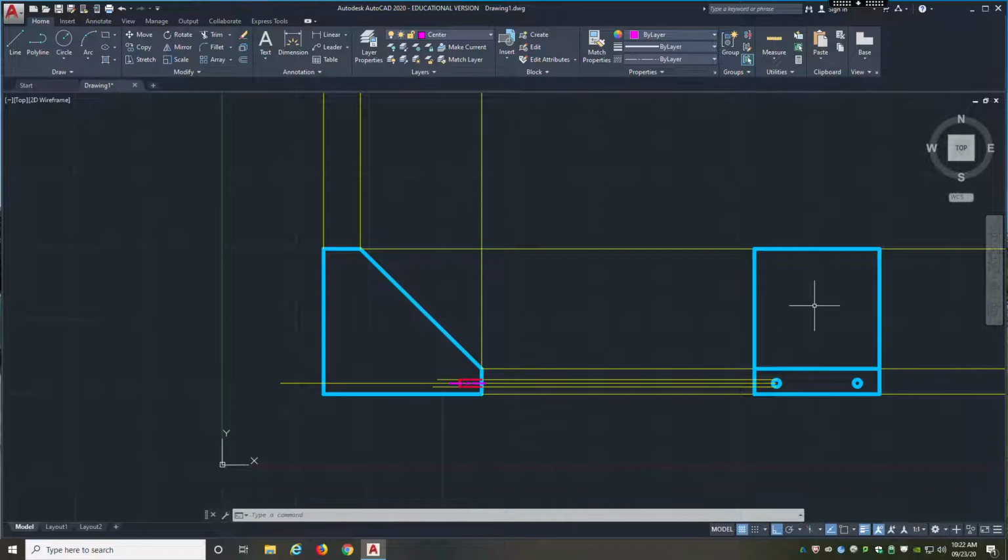Therefore, it's foreshortened, which is why a circular hole looks like an ellipse. So we can only get the horizontal information for that circle, and we need all the information for that circle.